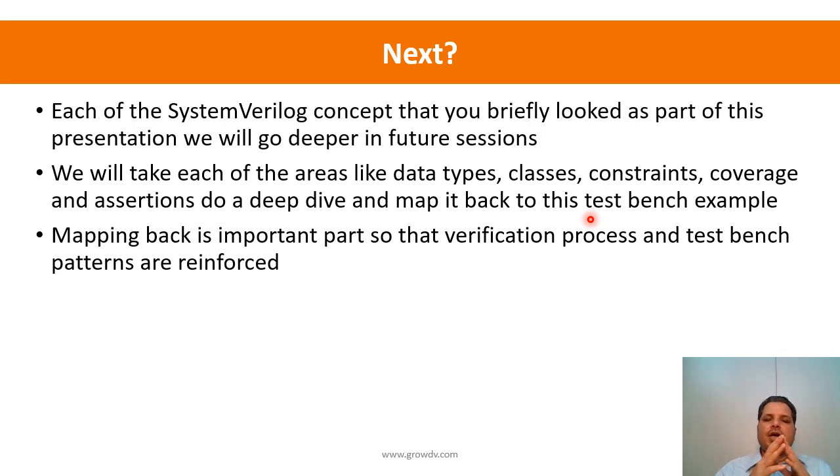For example, when we start looking at interfaces, we will think about the push interface, pop interface, and where the virtual interface was fitting in the test bench. All those concepts, we will now go deeper into each one of them. When we look at data types, we will come across a queue data type. What are the different methods available with it? Classes, like how does inheritance work? When we go into more detail, I want you to remember how we had applied inheritance to reuse in terms of tests. So all these concepts that you have seen already, the real life applications of them, from the constructs from a language perspective, what are the further features provided, we will look into it.